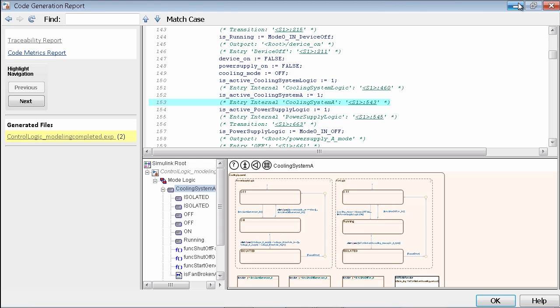So while we're on the topic of reports, for all the testing that you had done, generally I've seen our customers need to document their test results as well, or automate some of that testing and maybe tweak around the reports that they get as well, customize them to meet their company formats, add their logos and stuff. How much can we do any of that within our tools? Yes, if you want to customize any of these reports, you can, using the Simulink Report Generator tool. A lot of our customers leverage the tool to customize whatever they want from these reports. Out of the box, you get reports with each of these model verification steps. So the coverage analysis or code generation or test generation come with their own reports as well.